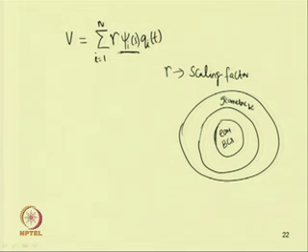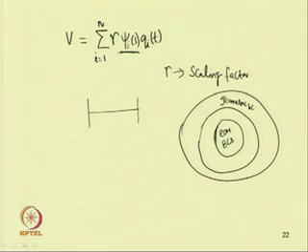So, in case of this continuous system, we have two different types of boundary conditions. One is the geometric boundary condition and the other one is the force boundary condition or natural boundary condition. For example, in case of this fixed beam, we have geometric boundary conditions at both ends, as the displacement and slope, which are geometric terms, are 0.